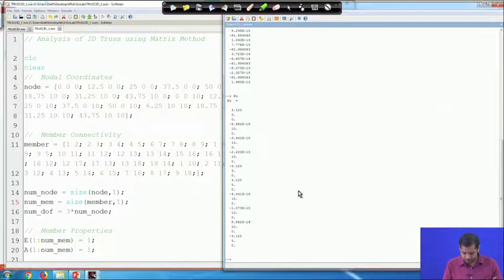If you join all the support reactions, the total load should be 0. Whatever load we apply on the structure in the corresponding direction, if we add them, equilibrium should be satisfied. It is a very important thing. When we derive this in the formulation, we use the equilibrium equation, so naturally they satisfy it, but the problem comes when you translate those equations into a code.